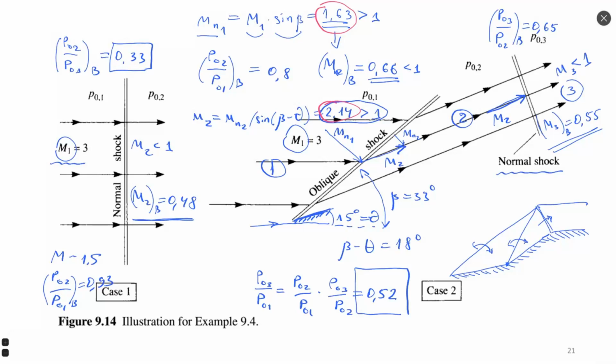I would like to clarify one more time. I already told this, but if it was not so clear, I would like to repeat it just to be sure. The goal of work one is to create favorable flow properties, I mean, to reduce possible losses of energy inside a 3 shockwave diffuser: 2 oblique shockwaves and 1 normal shockwave, as you may see here on this lower part. I already drew you this schematic before, right?